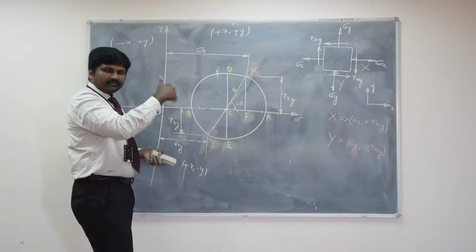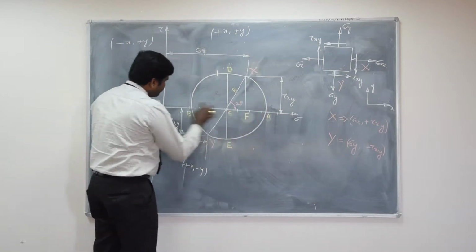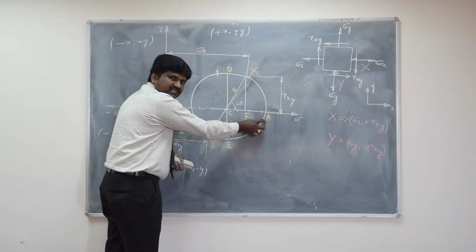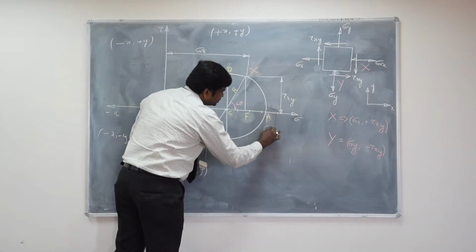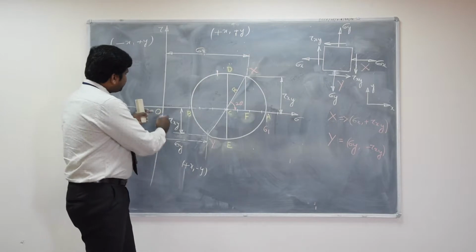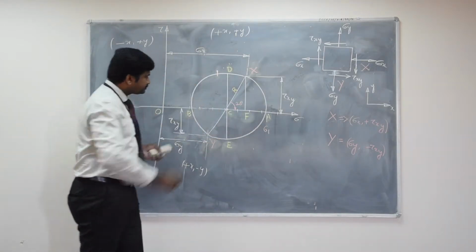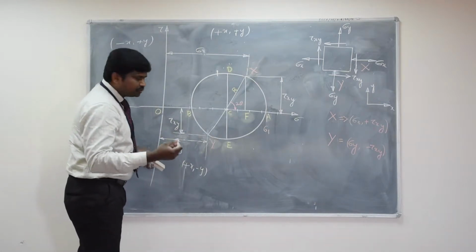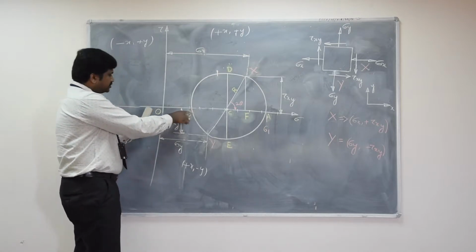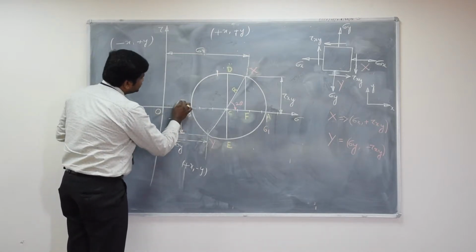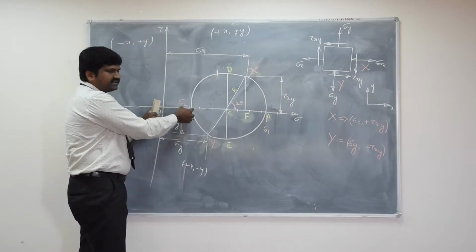That will give you the maximum and minimum principal stress. The farthest intersection of the Mohr circle with the x-axis is what is considered as sigma 1. Actually, this point here is sigma 1. So from where to where will you measure? You measure from O to A to the scale. You measure from here to here. Then where is point 2, that is the minimum principal stress? The nearest intersection to the origin is what is known as the minimum principal stress. You measure this distance to the scale, and you will get sigma 2.